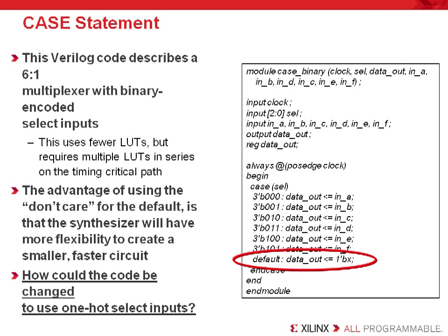This design also inferred a register on the data out signal. This effectively added a pipeline stage. Recall that this is one of the best ways to improve system performance in an FPGA. If this did not have a registered output, a critical path could evolve through this mux. It's usually best to always try to build the outputs of the lower leaf level boundaries with an output register.